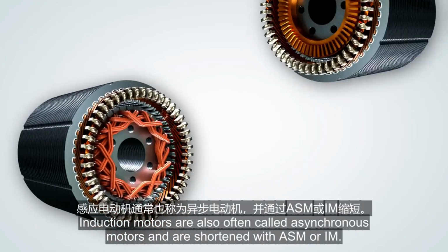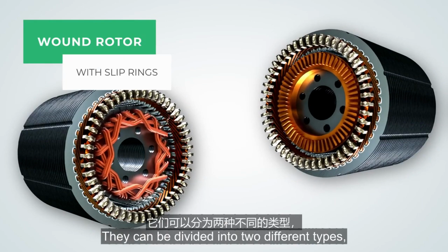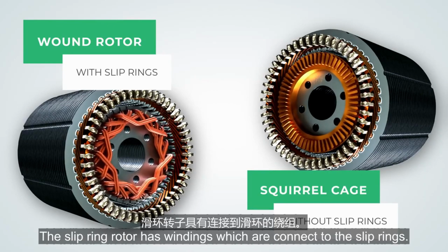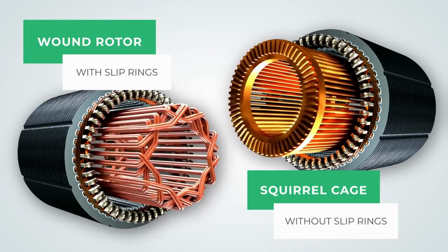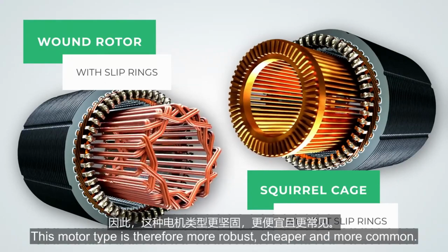Induction motors are also often called asynchronous motors and are shortened with ASM or IM. They can be divided into two different types, one with slip ring rotor and one with squirrel cage rotor. The slip ring rotor has windings which are connected to the slip rings. The squirrel cage rotor only consists of a short circuit cage and does not require slip rings. This motor type is therefore more robust, cheaper and more common.